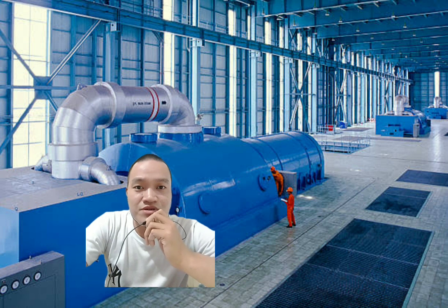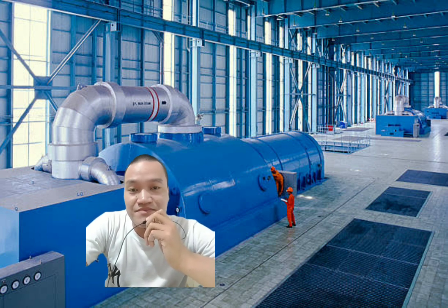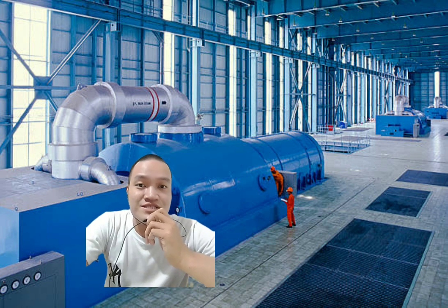The astern operation involves admitting steam to the astern turbine, where any considerable period of astern running occurs. Turbine temperatures, noise levels, bearings, etc. must be closely observed. The turbine manufacturer may also set a time limit of about 30 minutes on continuous running astern.